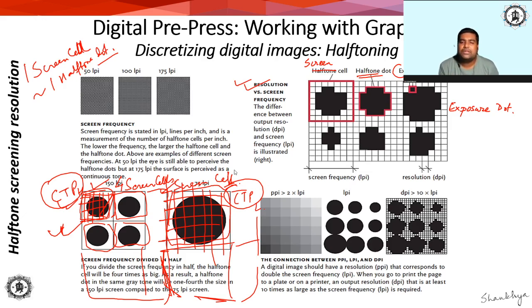If you have inserted the plate, some areas it will expose with the help of laser light, and the coating in the exposed layer will get hardened. If you wash it, unexposed areas will wash off, and the exposed area will become the image area. This is the same basic concept as normal platemaking, but here lasers are used. In surface preparation techniques you will learn in a lot more detail how CTP actually functions. That is different.